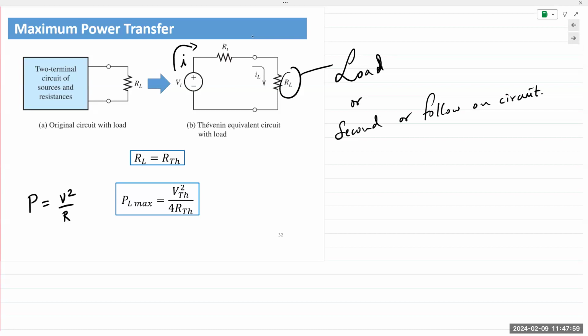It's supposed to supply 12 volts at its terminals, but more importantly, it should be able to supply current, because the ignition coil requires a large amount of current for it to actually start up. And so a car battery spec has cold crank amps. It will specify a temperature at which it will supply a specific amount of current, cold crank amps.